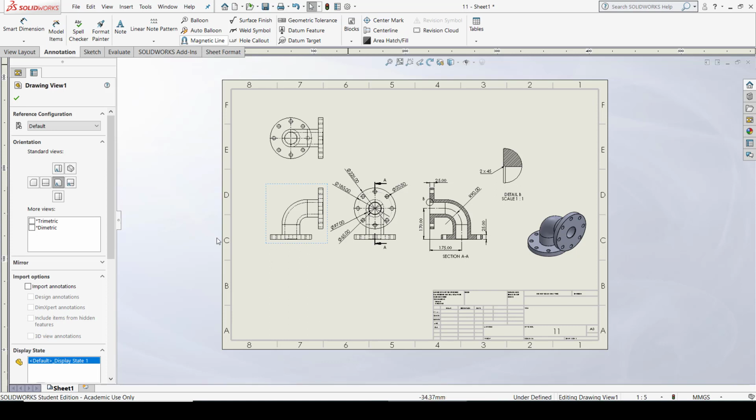Whatever changes you make in the front view, which is your major view, we call it the parent view, and all other views are secondary views. If you make any changes in the parent view, all the views have those changes. So when there is a change in the hidden line options, all the views have those hidden line options. Okay, so this is how you can define things in the drafting view.